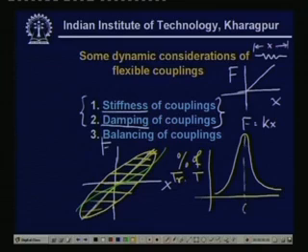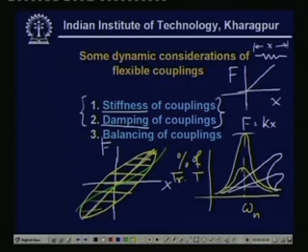That is, if the frequency of excitation, the exciting force, is almost equal to the natural frequency, we get a large transfer. But if you use high damping, then of course this peak comes down. If you use non-linearity, then you get this kind of relationship. So you see, using the non-linear, we can reduce this maximum limit to a large extent.